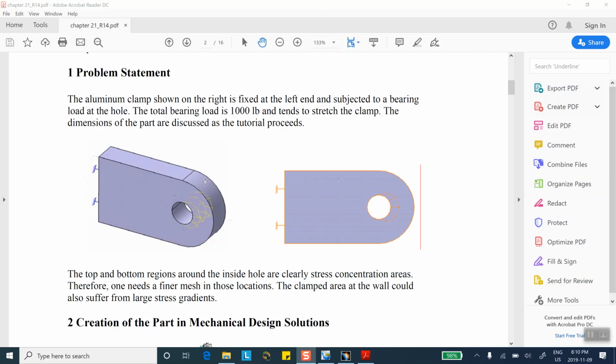That is a critical zone, and what we need to do is select a fine mesh in that area to be able to resolve this stress gradient. Of course, if we know where that area is, then we can go ahead and refine it and keep refining it until, in our judgment, mesh convergence has been achieved, and we stop there. But the more systematic approach is to let the software refine the critical area, and this is what is called adaptive refinement.